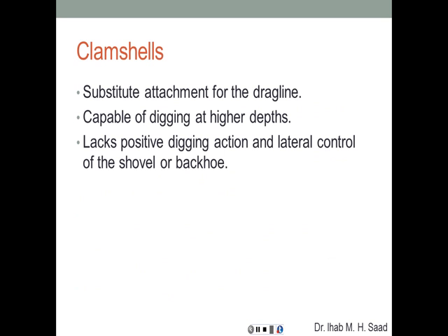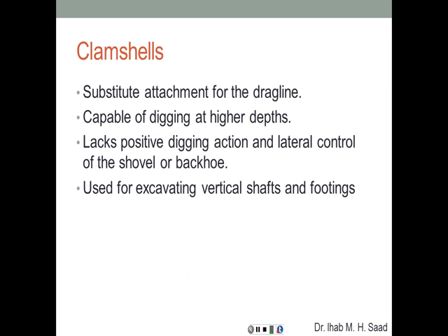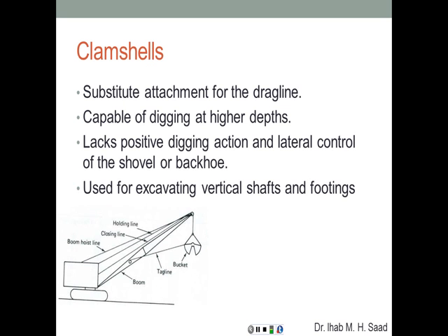Again, positive digging means the articulated hydraulic arm is going to give that hydraulic force, that crowding force, but in this case it's going to rely, like the dragline, on its own weight and on gravity. It's used for excavating vertical shafts and footings for foundations. So this is what it looks like.